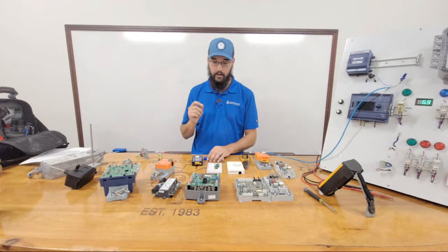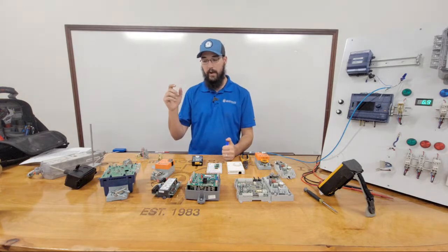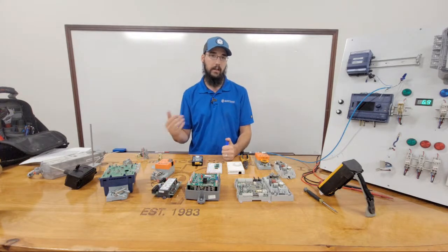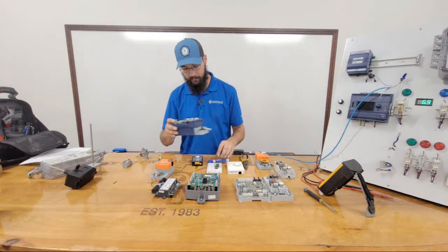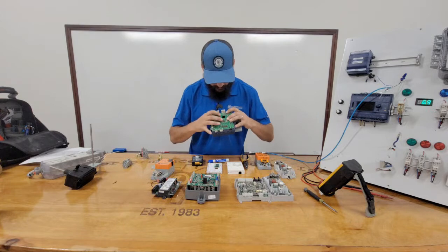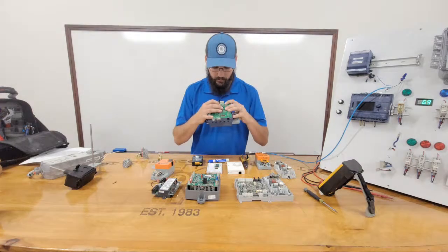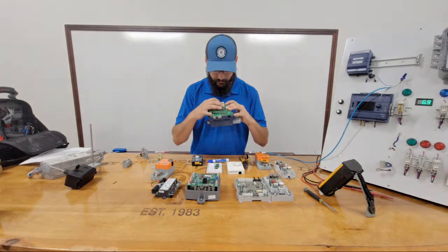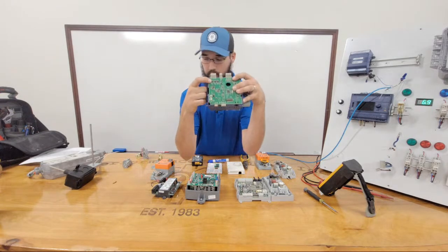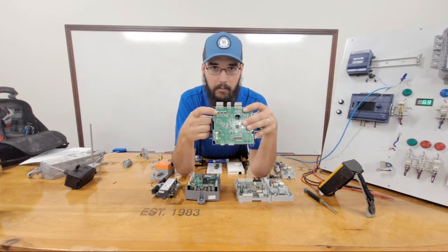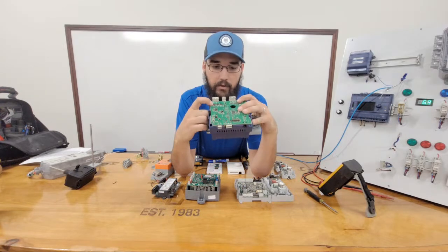You also have to be careful. You have universal inputs and outputs as well. Universal inputs and outputs, which are going to be these little circuits, they also have little transistors and triacs in them. I don't know how well you can see that here, but these big black boxes are your full-size triacs.